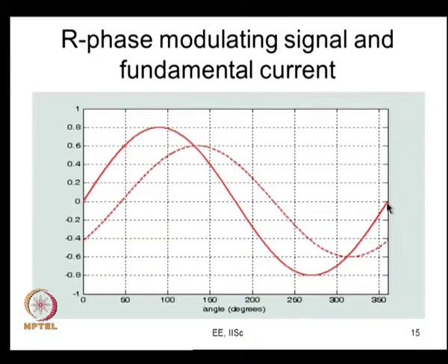Let us say that is being fed to a 3 phase linear load, so it draws a sinusoidal current. This represents only the fundamental component of the voltage. There are also harmonics. Those harmonic voltages would cause harmonic currents, but we assume that the load filters them out very effectively, since they are at high frequencies. So, effectively it is only the fundamental current that is being considered here. Let us say this is the fundamental current. As I said, there could actually be a small ripple, but you can ignore that now.